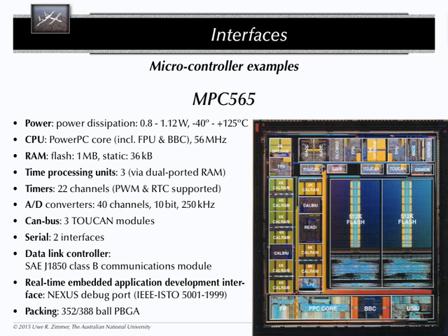So having a live view of what is going on in your system is now almost for free, as long as you have a device which can hook up to this standardized debugging port. Cool, huh? Instead of ripping this whole thing open and having a gigantic logic analyzer plugged into the whole thing, you only need to have something which is fast enough to run this serial communication to the whole thing.